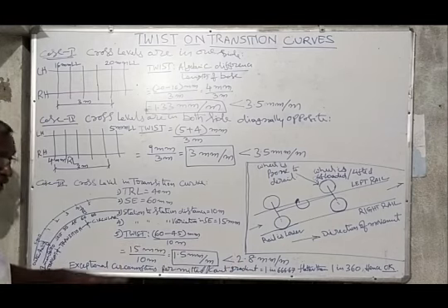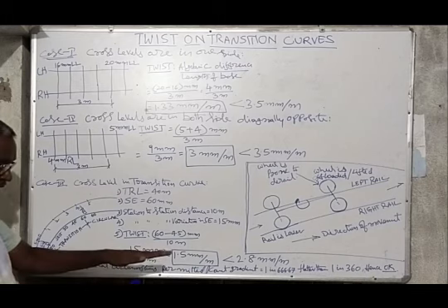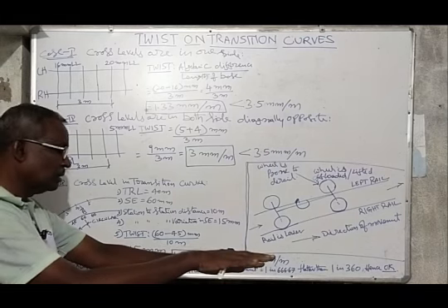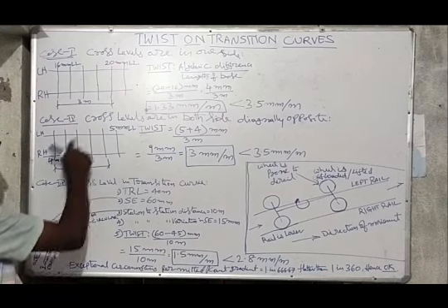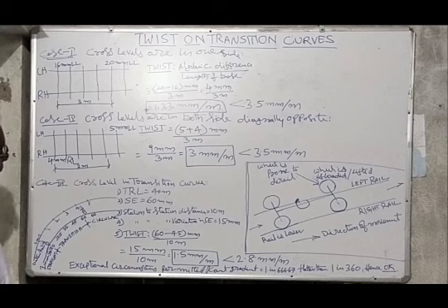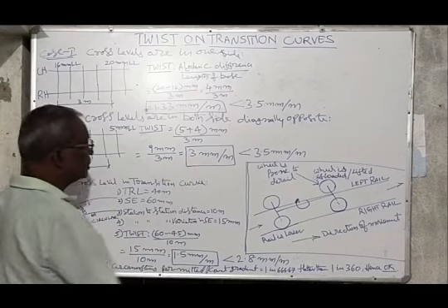So this vehicle is moving at such a faster speed from this orientation to again this orientation. So here the twist is more, 4 plus 5, 9 mm per 3 meters. 9 mm per 3 meters means 3 mm per meter.